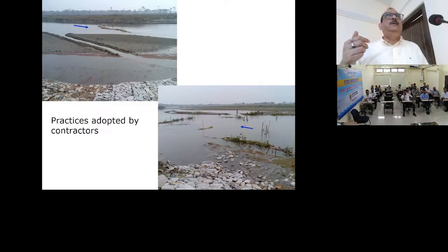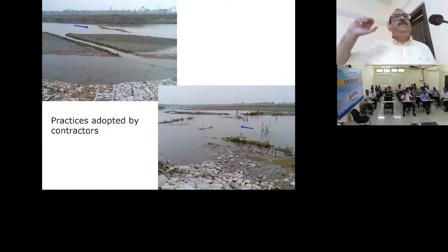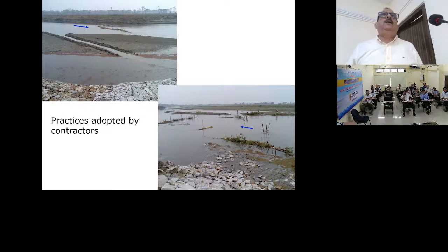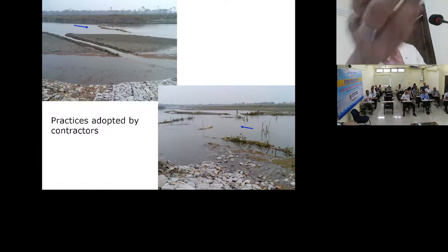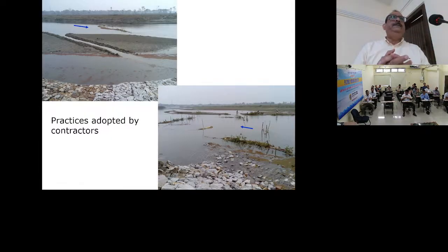No, no. They will remove these things. During construction, they have done this. Actually, while designing this boulder rip ramp, we calculate the different depths. At what depth we should place this, what should be the bottom level of the boulder, top level of the boulder. These things are calculated. And these things are related to riverbed level, HFL.